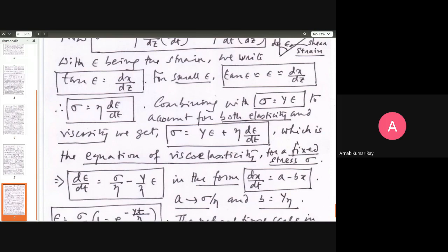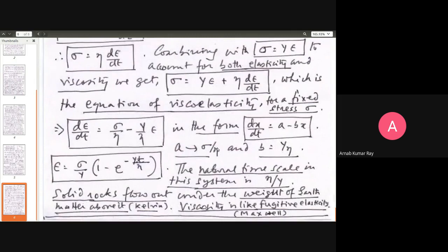So that is the thing, that you have certain materials where both elasticity and viscosity are displayed. Such materials are known as viscoelastic materials. I will give you a simple example. I believe that you've seen road work being done, road repairing. With the help of road rollers, stone chips are put on the road, and then the stone chips are made to stick to one another by liquid black tar, right? Now, this black liquid tar is an example of a viscoelastic material.